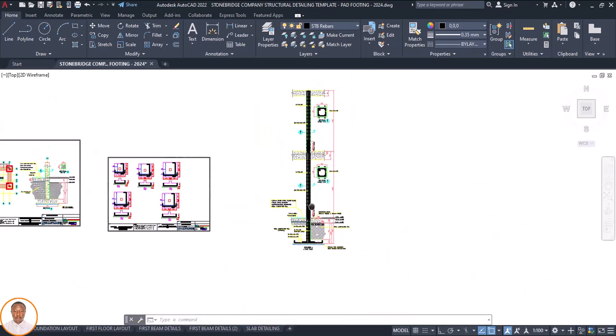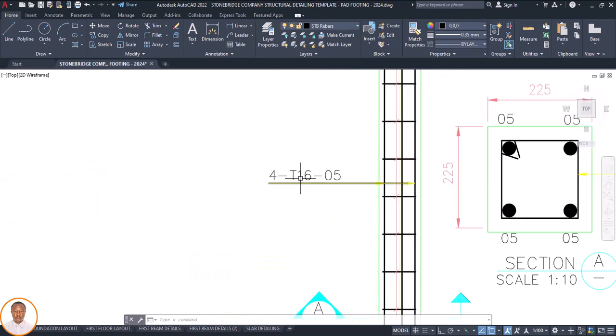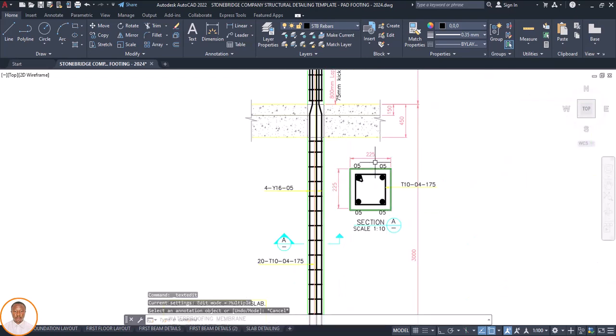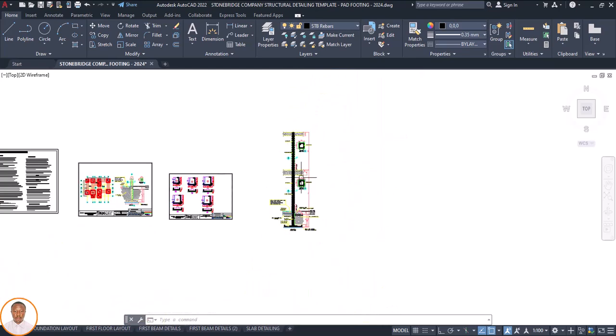So that is that. Anything you want again is 4Y16. Let's check. 4Y16, 4Y16. You can see 4Y16 is okay. If you now want it to be named with tag Y16, you can also put this one Y16. So that is that. Now you can see the same section. You can see it's okay. Everything's okay. With this, I'm done.